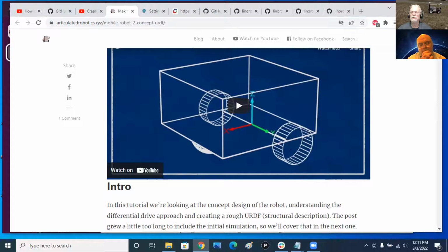So now that's all well and good for a little differential drive robot. So now I want to build the 4-wheel Ackerman steer vehicle. And it looks to me like if I make the back wheels work just like the wheels on a differential drive, essentially I instantiate them, put them on the vehicle, and put them across base link. That takes care of the back end.